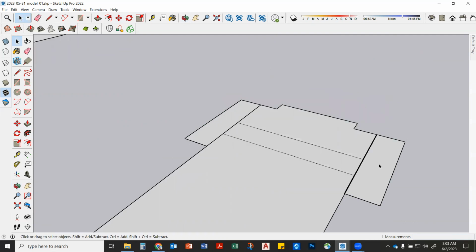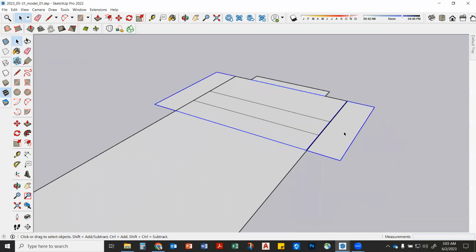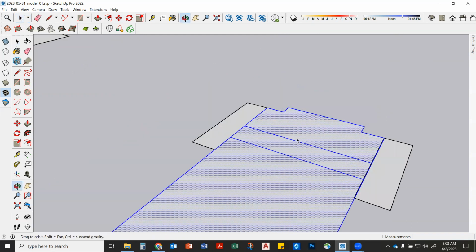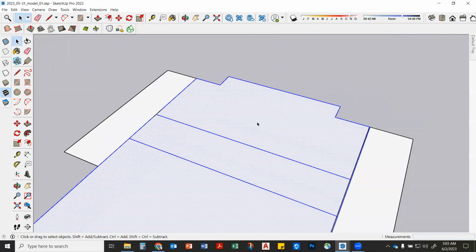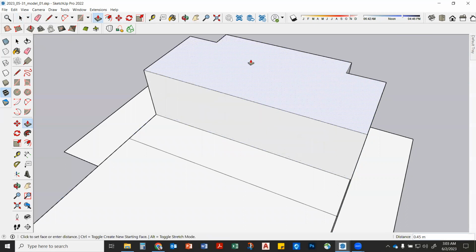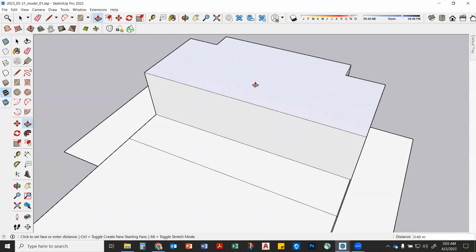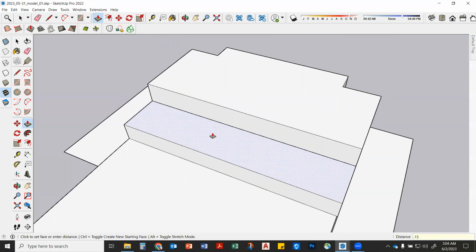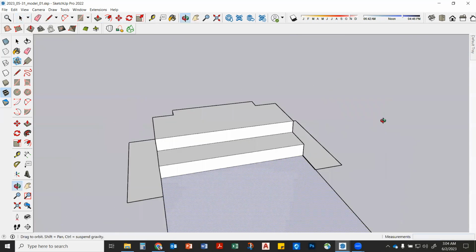So we're right here, right? Everybody? You got these guys as a group, and then there's components inside that group, right? So, we have line work right here. We can go ahead and push up. This is going to be the top step where the building comes in. We're going to hit P for push, click once. And that's actually going to be two risers, so that'll be 0.3, enter. And this one will be one riser, so click here, ready to move, we hit 0.15. Okay.